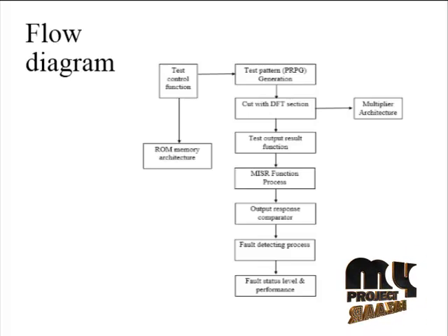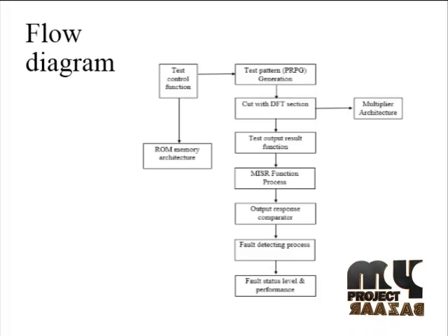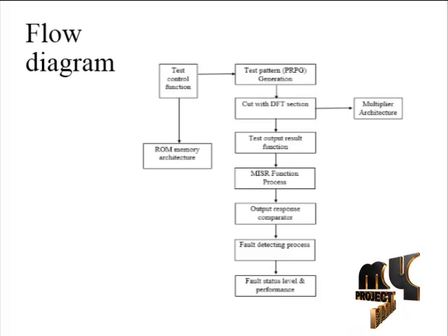For test pattern generation, we use PRPG. The data we give is 16 bits of length, multiplied by 8 bits, and the output will be 16 bits. In the MISR function, the process compiles all outputs into one LFSR. This works because LFSR is linear. It obeys the superposition principle. Superimpose all responses in one LFSR. The final remainder is the XOR sum of remainders of polynomial divisions of each PO by the characteristic polynomial.